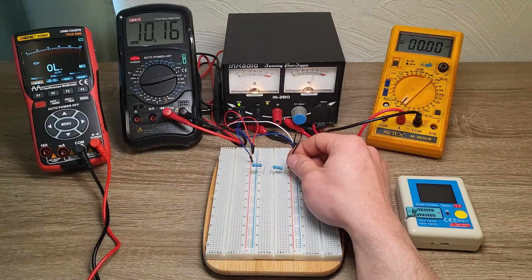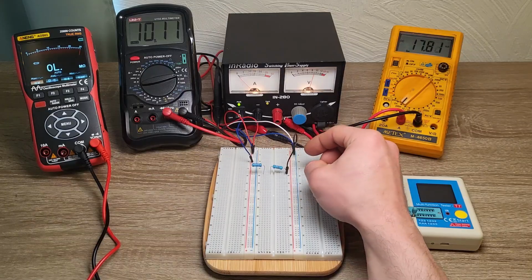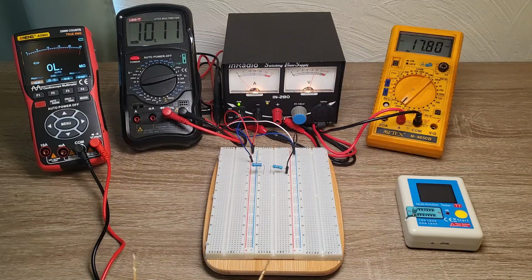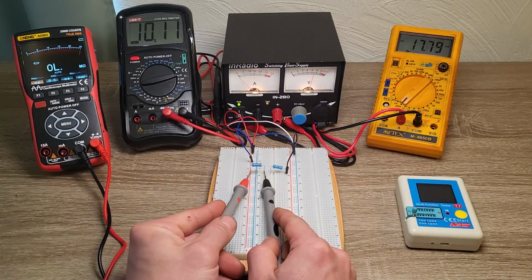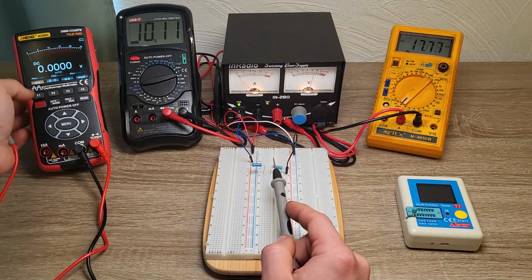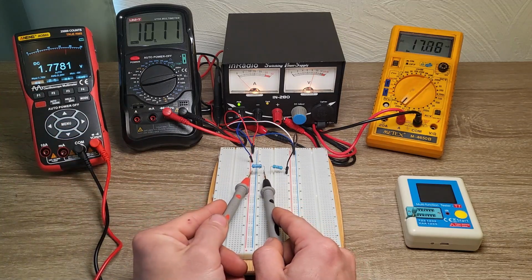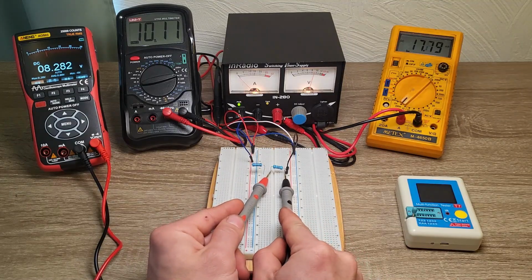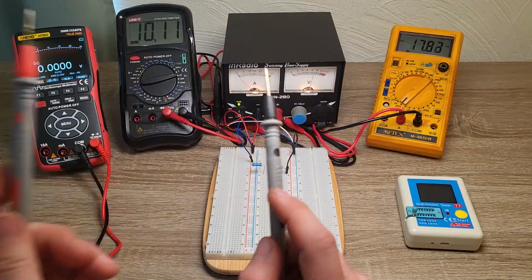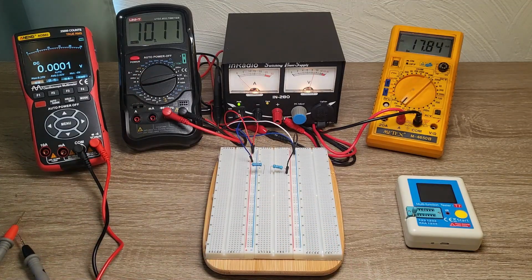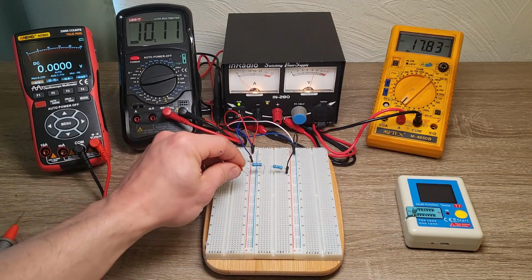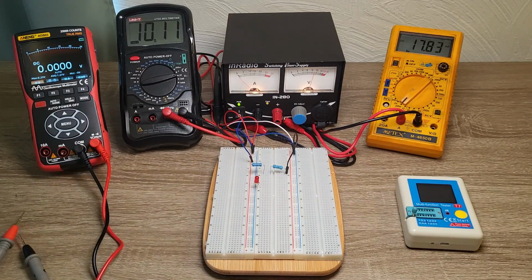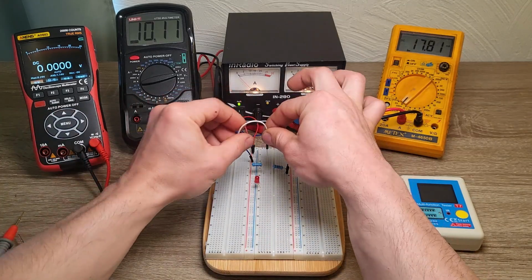First a power supply, later a minus, and we can see that on the first of the resistors the voltage drop, if I set it correctly, of course, will be 1.77 volt, and on the second one we are talking about 8.28 volt. What we can do, it's called a voltage divider. Now the voltage is divided in two different values.